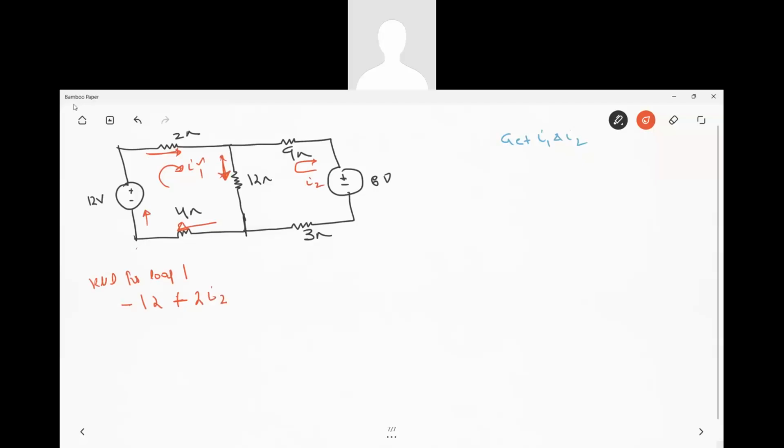Then here, plus 12 (I1 minus I2). Very good. I1 minus I2. This is the catch here. Then here, plus 4, I2? Not I2. How will I2 come? I2 is this side, correct? I1 is this side. So here I1 only, na? In this loop, I1 only. Only this is the branch resistor. Rest all the things will have I1, right?